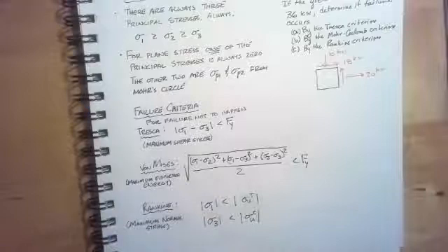The von Mises is a little more lax than the Tresca criterion, so it's possible you could have failure by Tresca and not by von Mises. You can still have a measure of safety with the von Mises criterion. It's just two different understandings of what two scientists believe to happen in materials as they fail.